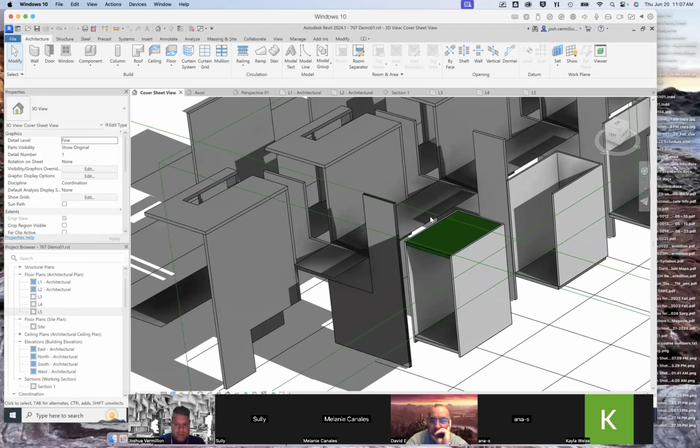Okay. Now, when you have a roof, there's ways of making holes in the roof: shafts, walls, vertical holes in walls, wall openings, verticals. So when it comes to something like this, where I cut a slot in the roof, and the slot looks like it wraps down and becomes the same sort of slot in the wall, here's what I would do. I would start to think about a vertical opening. It would ask me to draw the opening. Then I could do the same thing for the wall and draw the opening in the wall. Why don't I try that, since I'm still recording?